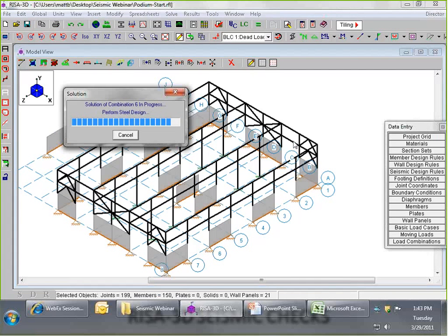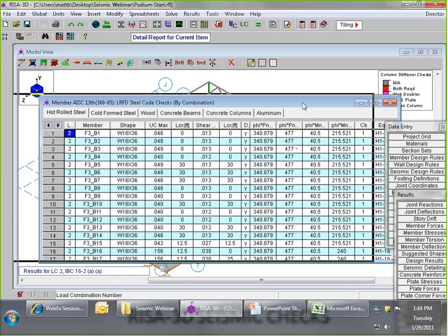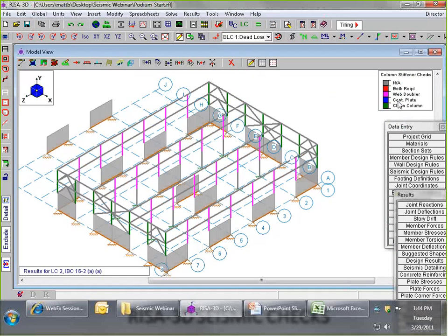Now, granted, we have gone up 24 pounds a foot in a column just in order to get rid of possibly some certain detailing. But I'm sure that if you compare the costs, increasing the column weight by a little bit in terms of the price of raw steel is nowhere near what it'll cost to have all sorts of extra web doublers or continuity plates welded onto those columns and specially fabricated.